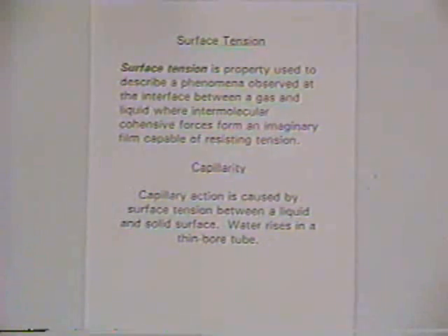And a related phenomenon is capillary action, and that's caused by the surface tension between a liquid and a solid surface. And you usually picture that as a thin bore tube. Water will rise up in the tube as the liquid adheres to the sides of the tube. Or in the earth, in geologic groundwater aquifer formations, where you've got sand and gravel and a water table, the water will rise up in the little porous media between the sand and soil particles due to capillary action.